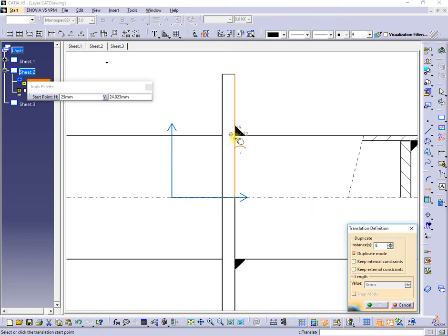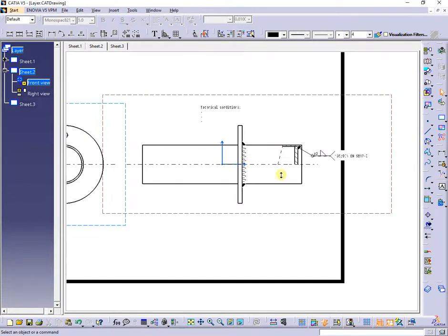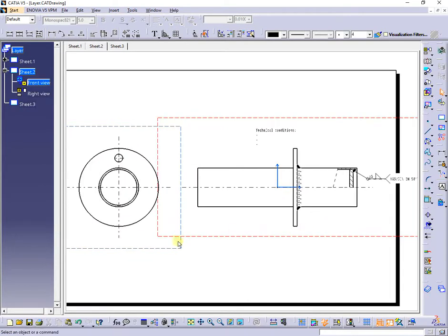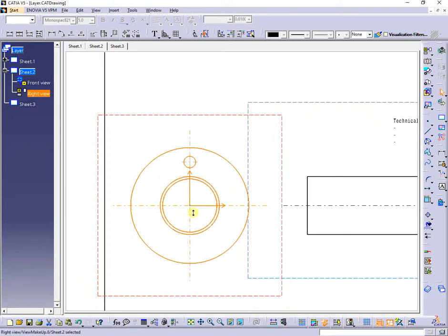This method I'm presenting here is easier because instead of selecting with multiple windows, with the Control key pushed, you can select in one window all the features visible after applying the visualization filter, without any fear of selecting other unneeded geometry. So you don't need to clean unnecessary objects after pasting data.